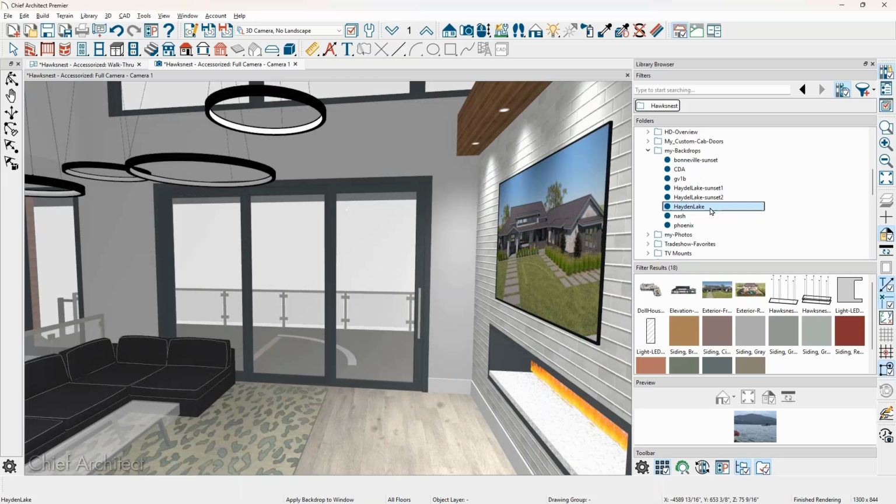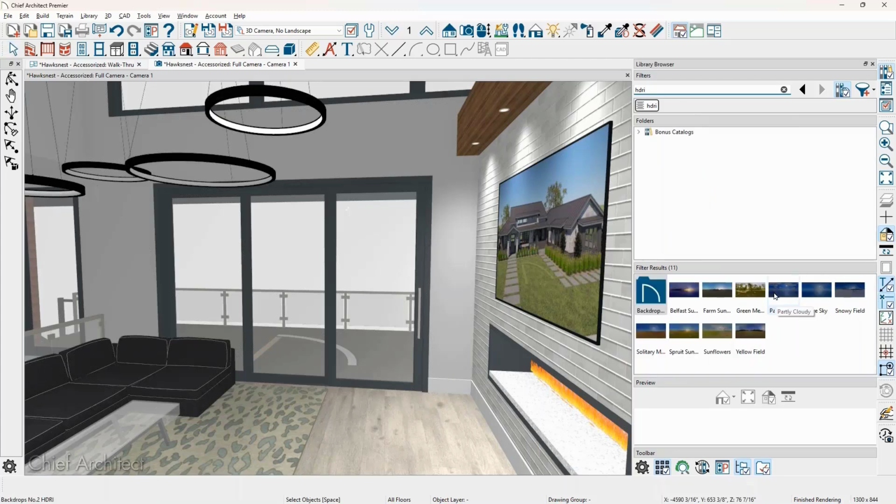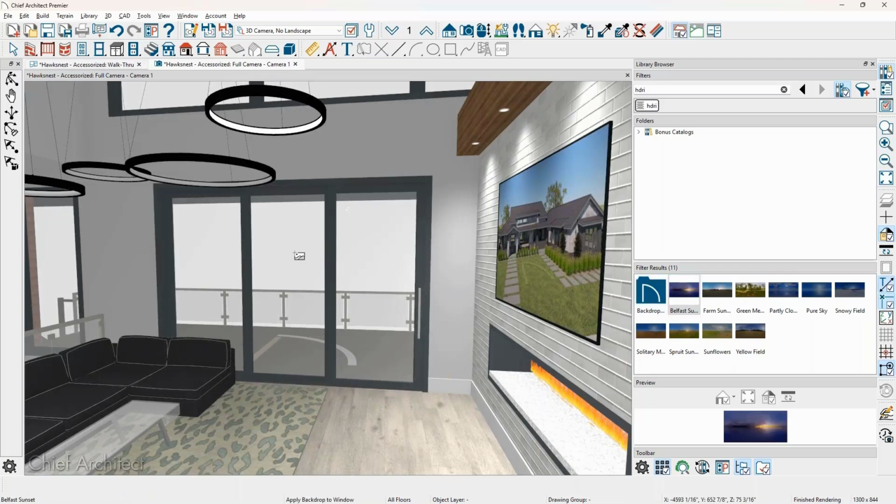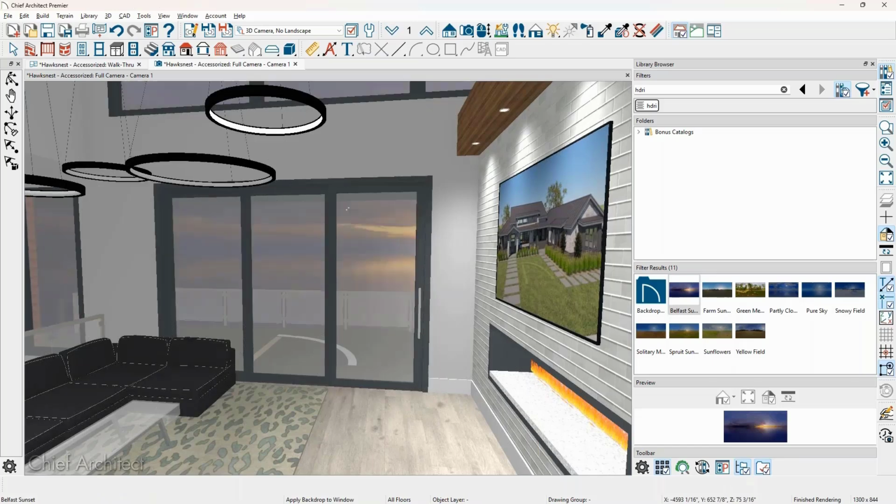See if that one's panoramic. That is not. So there's a setting. Let's see if I have one in HDRI. One of our users says maybe HDRI. Yeah, that's what I just found here. So I'm going to grab one of the HDRI backdrops and drag that into the scene here. So just click and place that into the scene.